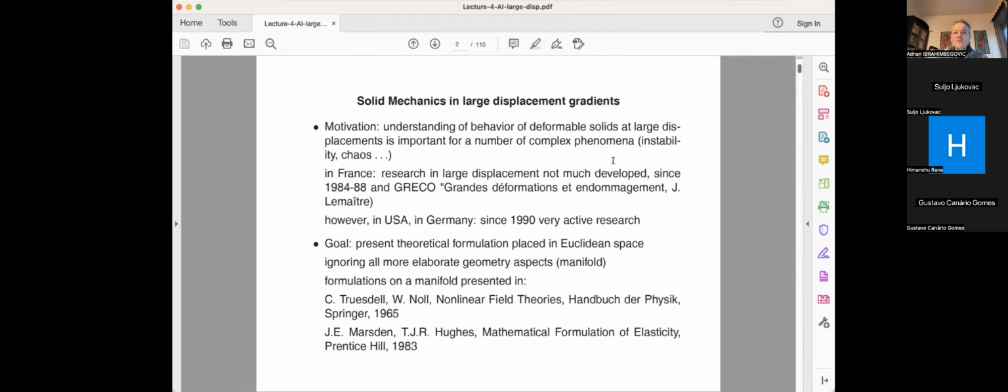This is not without importance, because if you take a finite element discretization, you have to deal with so-called locking phenomena. We already discussed this in different applications. It is an inability of the polynomial approximation to represent certain deformation modes, especially a mixture of different deformation modes. So you want to keep this expression as simple as possible. If you have curvilinear coordinates, where even the unit vectors are not constant and the derivatives start producing additional terms, as opposed to fixed Cartesian coordinates where the derivatives of unit vectors are zero, then you certainly have more difficulty picking up the right interpolation.